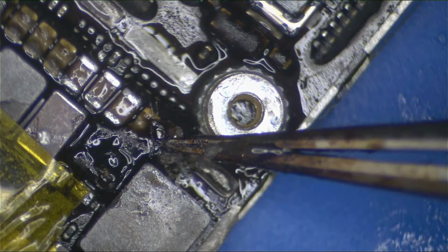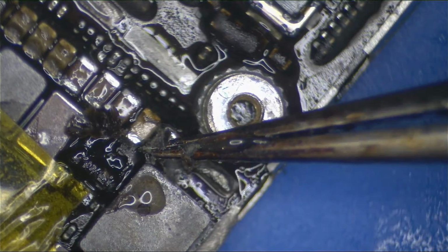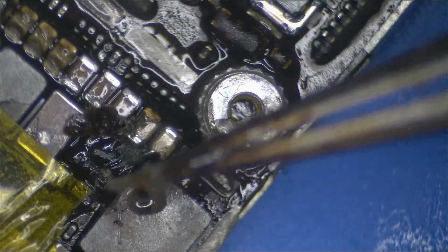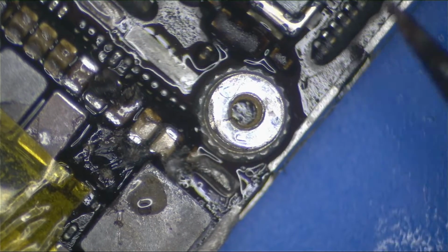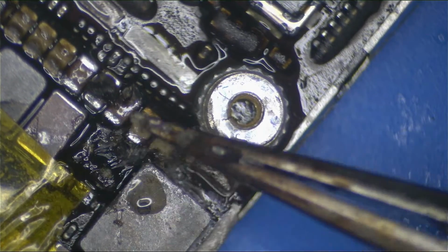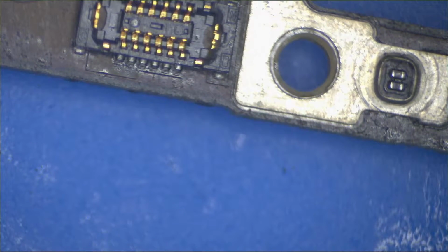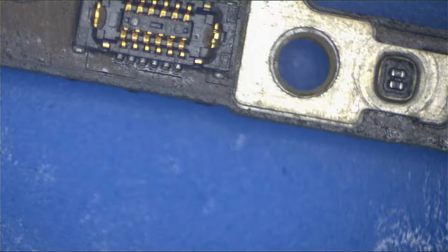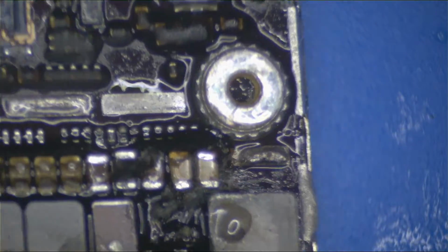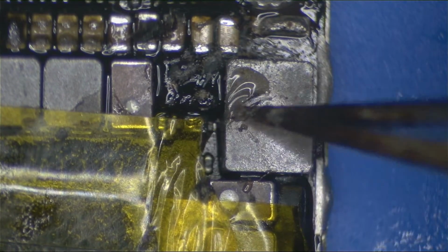And yeah, this takes a while. I mean, you can add a little bit of heat sometimes, or use your hot tweezers, or your iron. It really depends on what you want to do. You don't have to remove everything, just enough so that, for the most part, it doesn't hold the coil in place. It's kind of a bitch, but I don't know why Apple did this honestly, because it doesn't seem to make a difference besides just annoying us. But it's there. So yeah, that's the coil there.